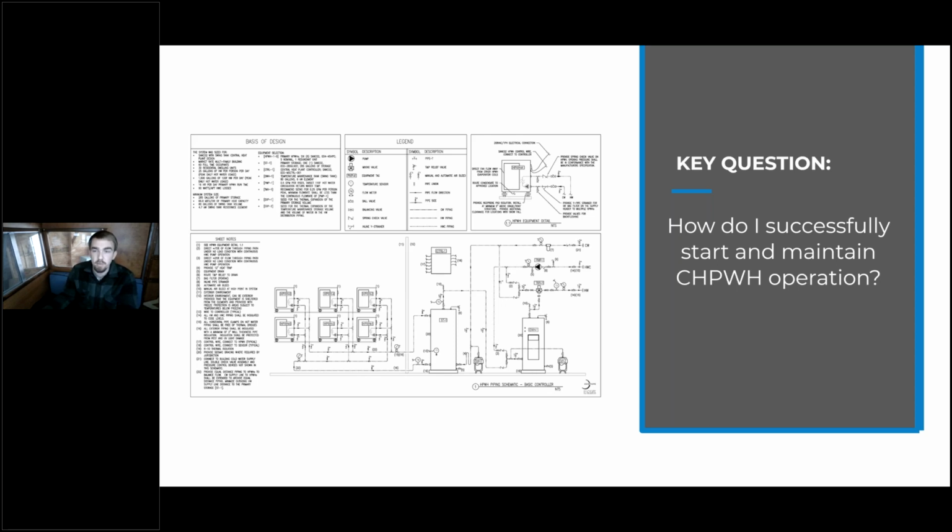Another thing to think about during the startup process is your conditions might be different between startup and the majority of where your heat pump's operating. You might start it up in the middle of summer when it's 80 degrees outside, but you need to follow up the following winter when it's 30 or 40 degrees and the heat pump is seeing much different conditions than when it was started up in. So we'll go a lot more deeply into these points, but we just need to make sure we're thinking about the question of, how do I successfully start and maintain the operation of these systems?